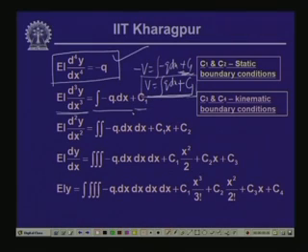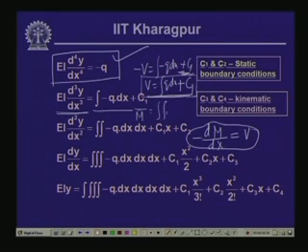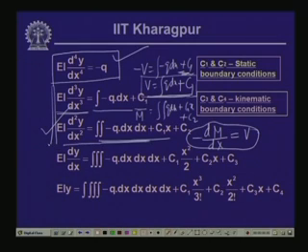This particular expression we had arrived at from the equilibrium of a small section taken out from the whole beam. So, this expression represents the equilibrium of the loading system. Subsequently, we have seen that the derivative of the moment is equal to shear, V equals minus dM dx. So, from this expression, we can get M as the integral of q dx plus C1 x plus C2, and this is our moment E I d2y dx2. Hence this set of equations represents the equilibrium of the beam segment, and further integration of these gives us the value of the slope and corresponding deflection.